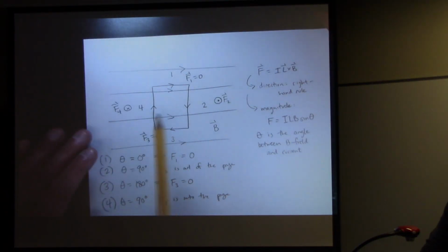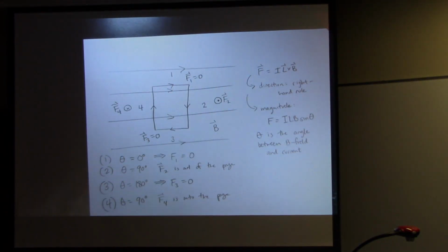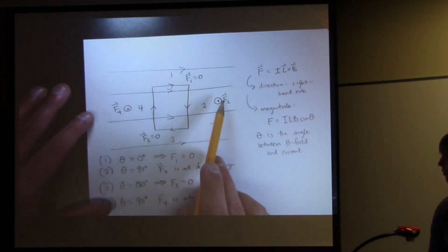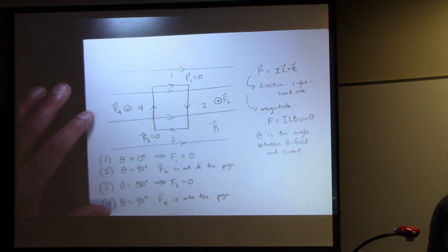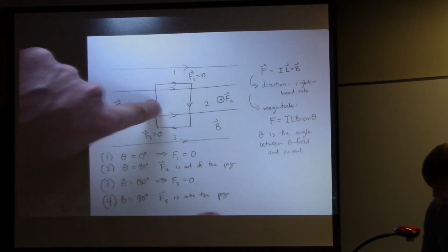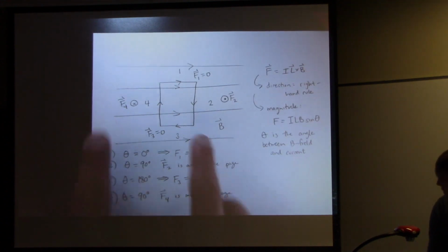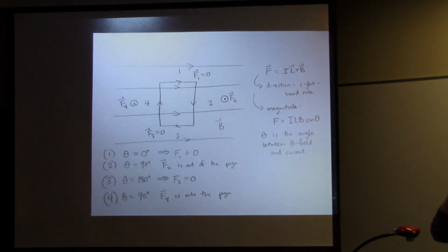So apparently, that's what's happening here. This coil that's carrying this wire in this magnetic field is feeling a force this way, it's coming out of the page, so it's like you're pulling this side up out of the page, while at the same time, you're pushing this side down into the page. That's going to make it rotate. That's going to make it spin. And that's the actual basic principle behind an electric motor.